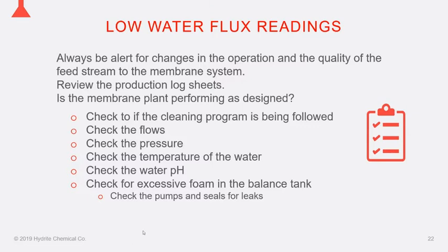Water temperature: are you getting the proper temperature for cleaning? Is it not too hot? Is it not too cold? Is it just right? And then the water pH. Different water supplies can have different contaminants in them. Are they using a good, fresh, good quality, low microbial count water to clean? Well, that will give you your best cleaning results. Did they have to switch to well water that maybe has some contamination and a lot of hardness to it? That can cause problems as well.